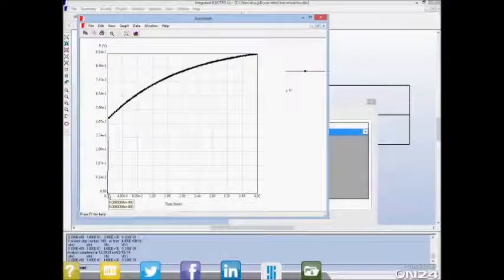So what you see here is as soon as it's turned on, because we have equal insulators, equal area, and equal dielectric constants, the instant it's turned on, ignoring signal propagation down the lines, both of them have an equivalent effect, and therefore the voltage in the middle is half a volt. The voltage divides evenly between the parts.